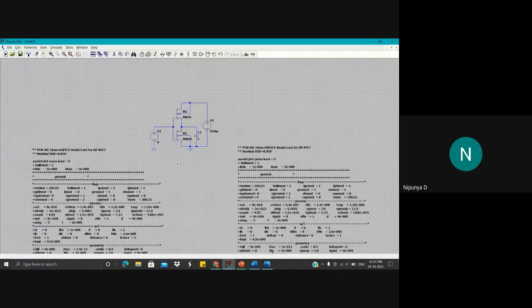And here you just got to know that there are many types of analysis that we can do. So we will be using this one circuit and we will be doing three types of analysis, that is DC, AC and transient. So let's start with DC. For DC analysis, we will be sweeping the gate voltage from 0 to VDD, and we know how exactly that works, right?